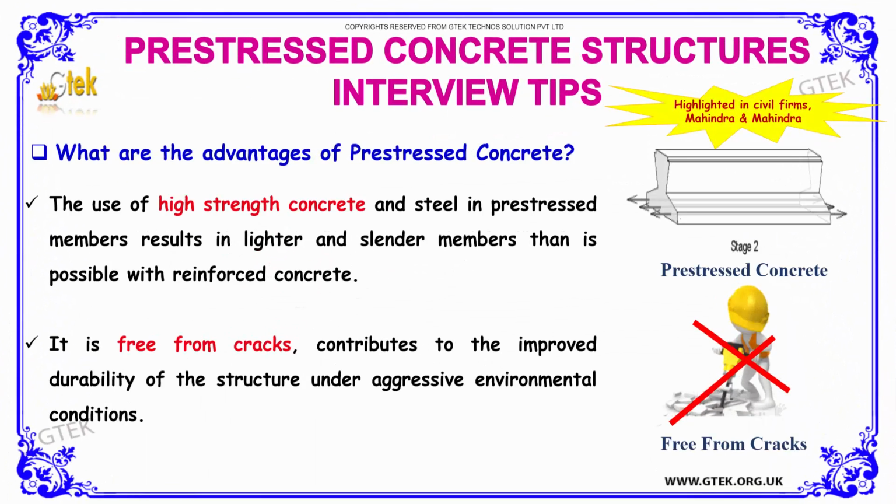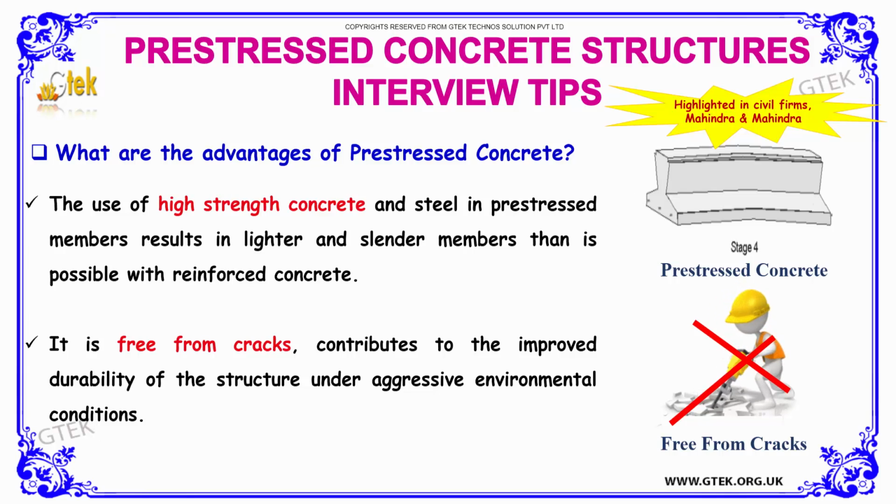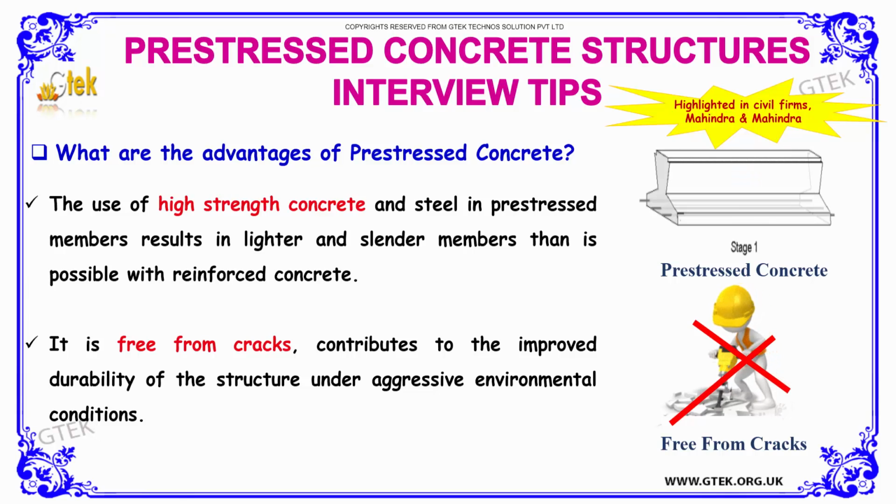Let's move to the next question. What are the advantages of pre-stressed concrete? So the first and foremost advantage is high strength concrete. The use of high strength concrete and steel in pre-stressed members results in lighter and slender members than is possible with reinforced concrete.